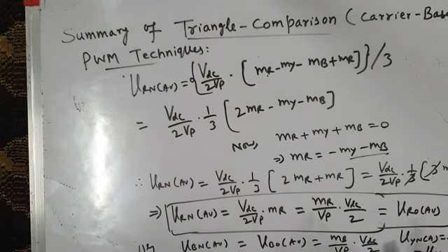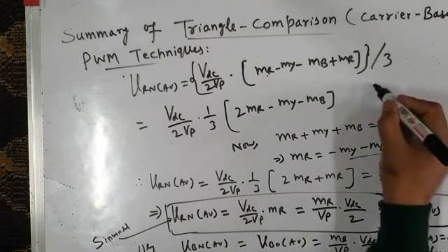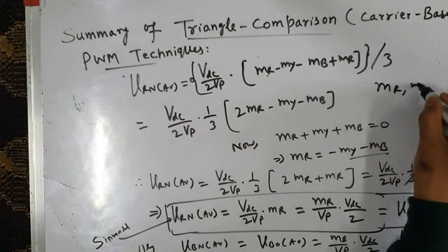So therefore phase voltages are the same as pole voltages, and since your pole voltages are sinusoidal, your phase voltages will also be sinusoidal in nature. So we have found the instantaneous average pole voltages, line voltages, and phase voltages for a three-phase PWM voltage source inverter, assuming that it is modulated by sinusoidal target reference waves, or sinusoidal modulating waves Mr, My, Mb.